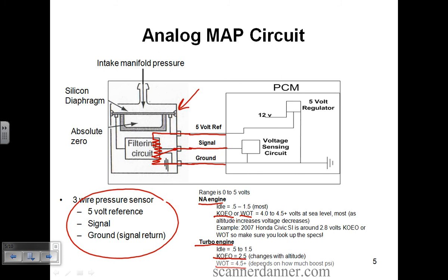What we look for, that checklist I've been talking about. What's our checklist? ECT, IAT, TPS. We actually did it yesterday on a Honda we had in here with an idle surge. We looked at the coolant sensor first. Why? Because we had a fault code for it. Well, we didn't know the guy was unplugging things, but we went through this checklist real quick. Okay, ECT, good. By doing a simple voltage check, we had numbers in our head. It said 3.2 volts cold, and what was it? 0.6 hot, if I remember. And we read 1.5 volts. Okay, check mark.